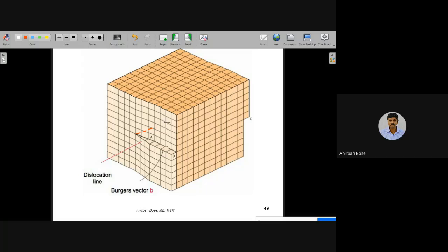If you consider that line throughout, around that region with respect to one another, there will be a shear. So a kind of shear force will act. It's a pure shear that will be observed under this situation. Previously, in case of edge dislocation, you observed that it is pure tensile and compression around that line. And here you can understand that there is a shearing force. If one part is moved with respect to the other part, this is the shear.